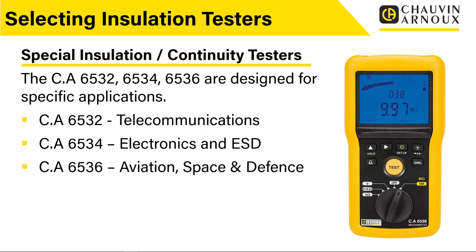The 6534 is designed more for electronics, particularly ESD, electrostatic discharge. If you're setting up an electronics production or repair environment, you will have things like static dissipative matting and wrist straps to dissipate any electrostatic discharge. They need to be tested. With suitable electrodes, you can put those onto the matting and test them. Again, that product is specifically designed to work in that environment and be very good at that job.